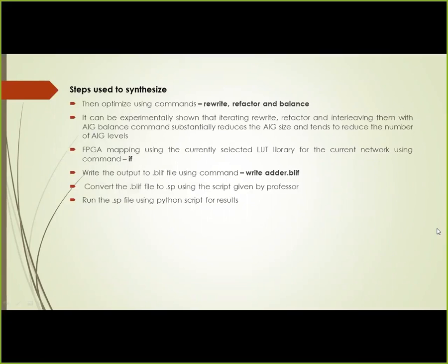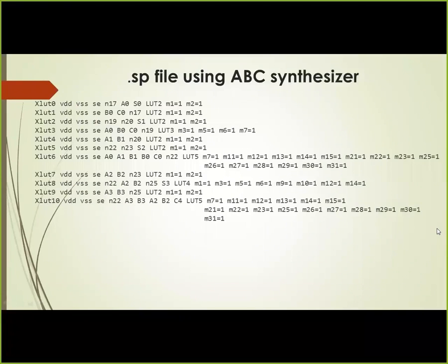It is actually minimizing everything, not just the best, but in terms of power, area, and delay. If you observe the netlist here, there are only a few LUTs, only 11 LUTs of different combinations. So the tagline is, if you use fewer LUTs, the better the results will be.